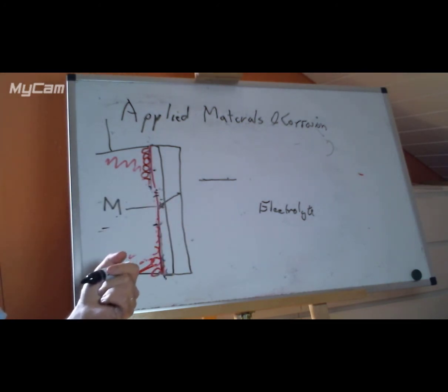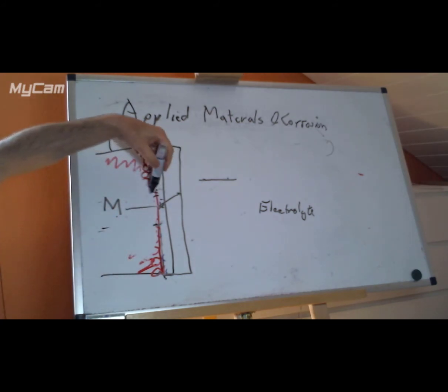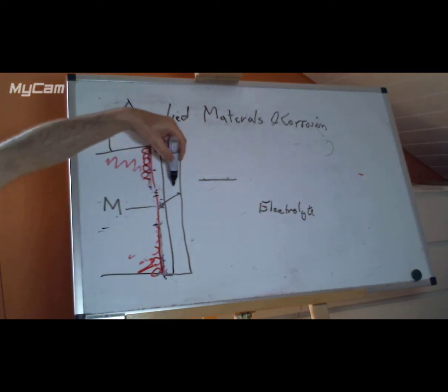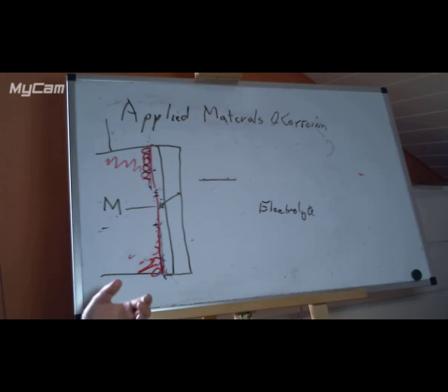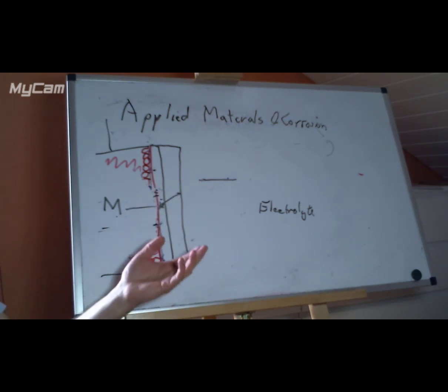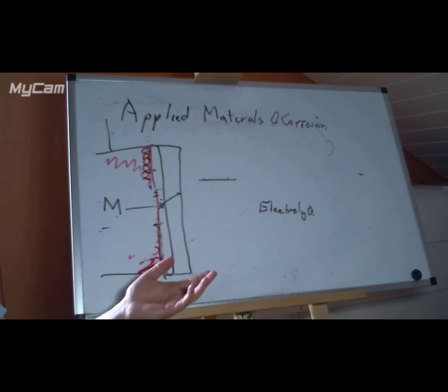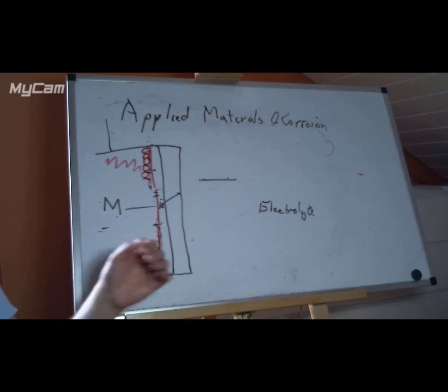So it's going to go slower and slower, or in terms of the ions moving through the oxide layer, the potential is also getting lower and lower, so they can't move as fast. If we make our system a little bit more complicated, we can imagine that the metal oxide is dissolving into the electrolyte. So if we have something like iron or even aluminium in slightly salty water, or zinc in somewhat salty water, we will be able to dissolve it eventually. So we will have loss of thickness.